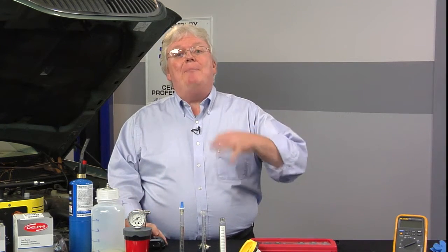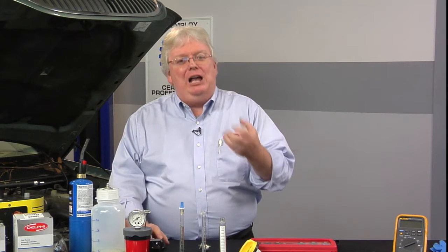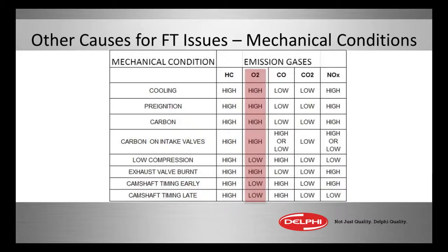But if it's just got normal stock parts in the engine and there's a problem, you've got an overheated cooling system, a head gasket issue, a valve that won't seat, those kinds of things, since most of us don't have a 5-gas analyzer. If you did, you could take a chart like this and nail exactly, by looking at all the gases of the 5 gases, you come up with the solution of what's probably causing the problem mechanically if it's not an air, fuel, or ignition issue.